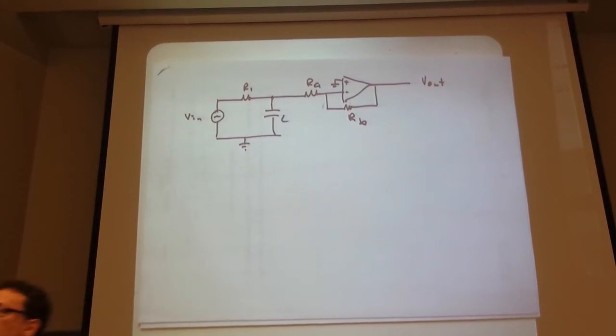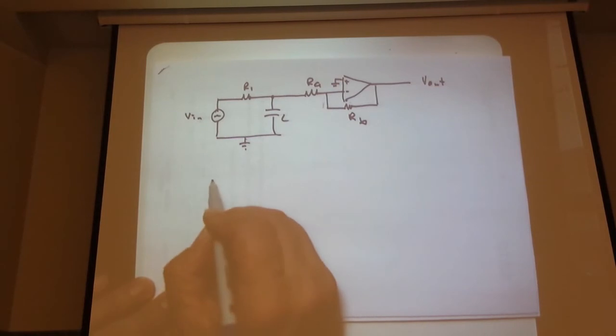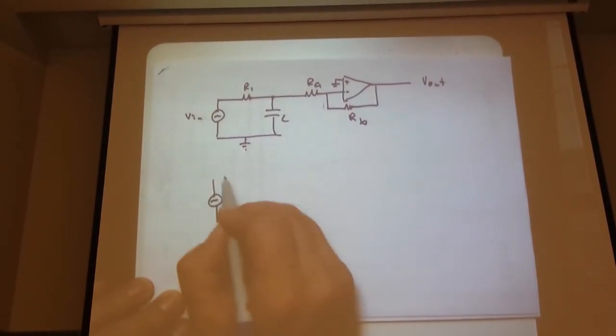How would I make this? How would I isolate the inverting op-amp? If you looked at the homework, maybe you know. How do we isolate the inverting op-amp from the RC network in the RC circuit? What do we introduce? A buffer. Or more specifically, a voltage follower.